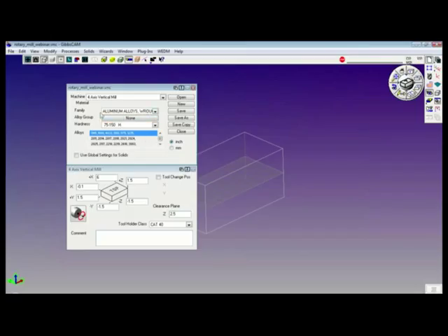To do so, I need to select the correct family. Aluminum alloys in the wrought condition sets up the conditions for the correct aluminum alloy grouping. The group in this case is none, but the hardness is selected as 75 to 150, the upper temper of the aluminum alloys. If I scroll down in this window, I notice that 6061 is part of my selection set. So if I use the material database in GibbsCAM, it'll give me feeds and speeds consistent with this selection set.